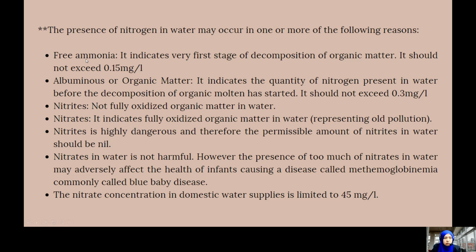As you can see, free ammonia in water indicates the very first stage of decomposition of organic matter. It should not exceed 0.15 milligram per liter.